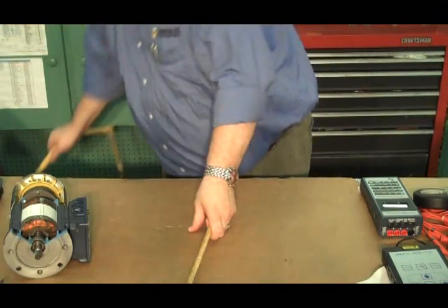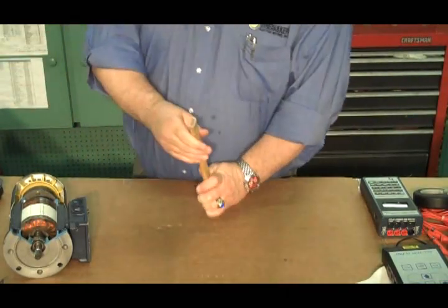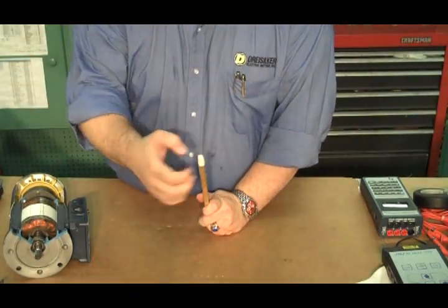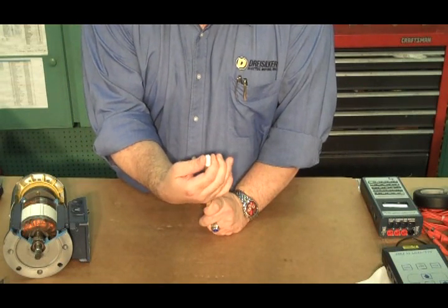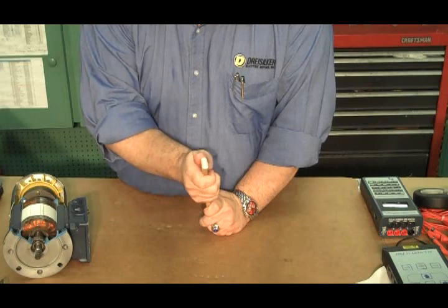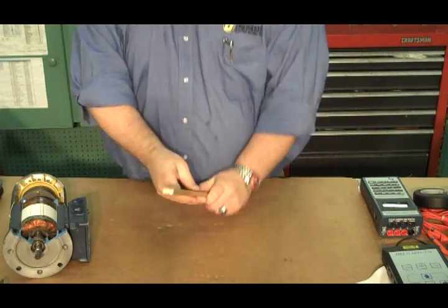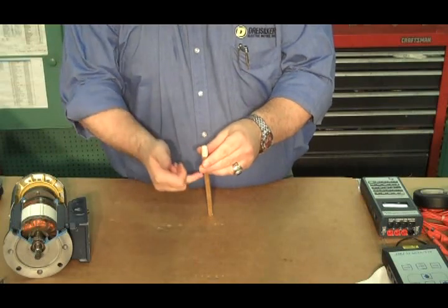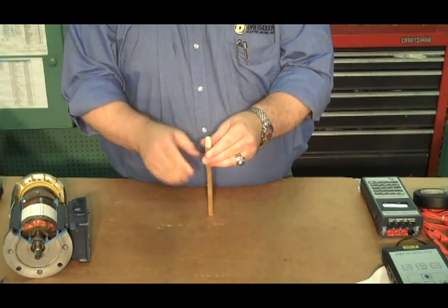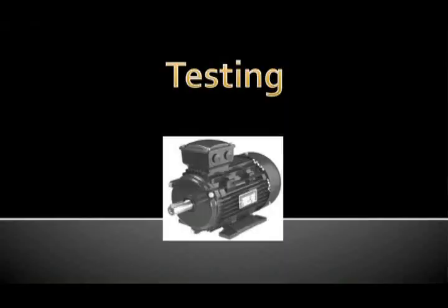That material is copper as well, but then that copper has a wrapping around it. That's the rest of my insulation system. This is usually referred to as an armor tape. Okay, and all of that is there to, again, get the electricity to flow in a certain direction, hopefully not to ground.